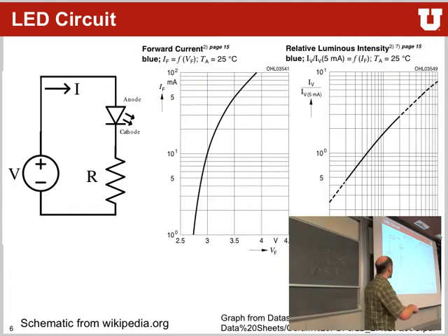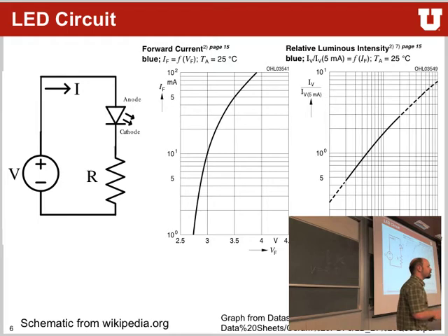So if you go, for example, to this particular data sheet, this is from an Osram 0603 LED. That's actually the LED that I'm using in that tutorial video. You can see that the forward voltage drop increases the more current. Is this right? Yeah, the more current that we are using. At the same time, we have more light. More light comes with the more current that's flowing through it.